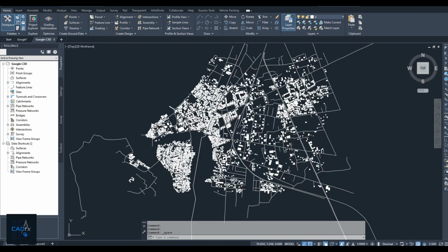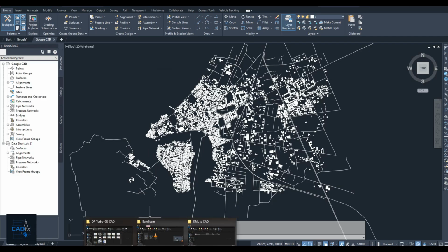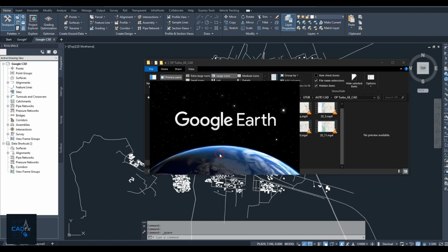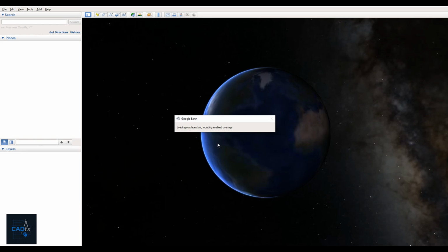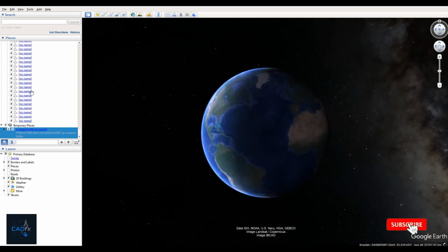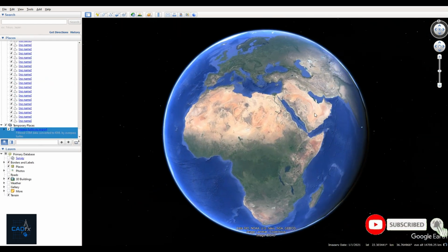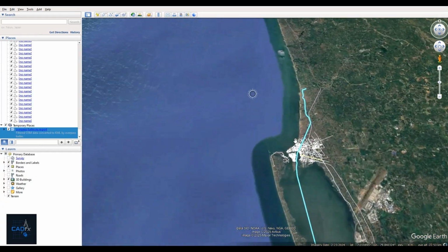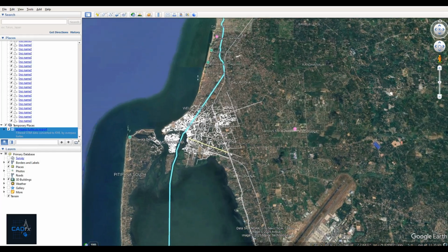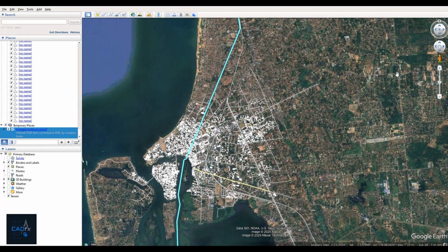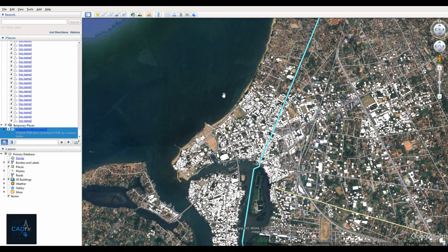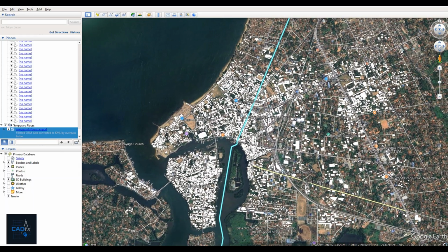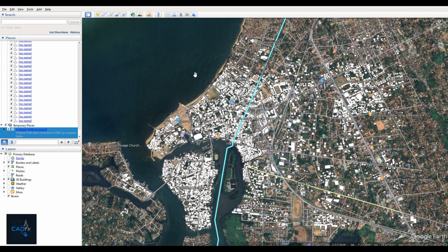Once the data was selected, we exported it as a KML file, which is valuable because it contains important objects with the properties. Next, we covered two different methods for importing that file. For AutoCAD, which doesn't natively support KML, we used a third-party LISP routine to successfully import the data. For Civil 3D, we used the program's built-in Map Import command, which makes the process much simpler and provides more control.